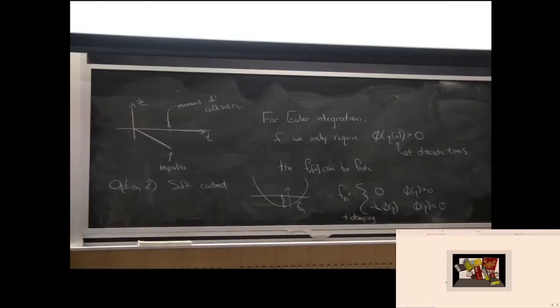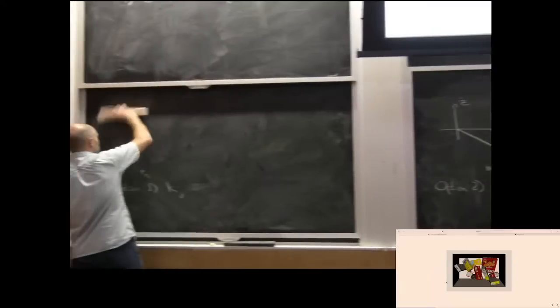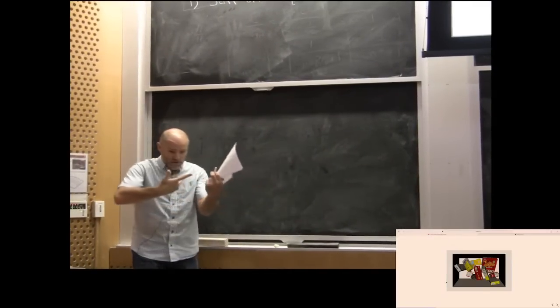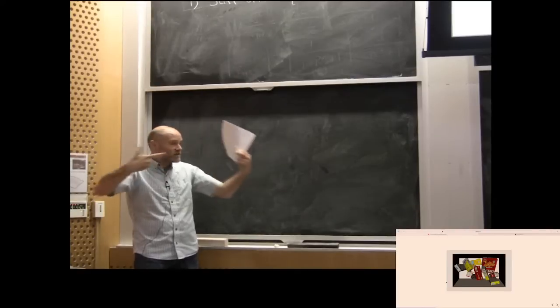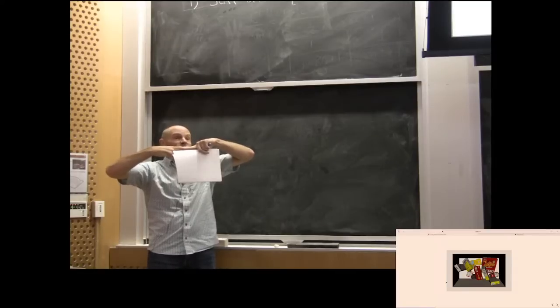Okay, so let's think now about friction. We've only talked about vertical force so far, where vertical is always defined in this frame as the direction of the gradient of the signed distance function. I'll say that more carefully, but in the ball falling from the sky, the normal force is always vertical. But for any two objects as they're coming together, the normal direction is the direction of closest distance, minimal distance. Okay, that's the generalization.